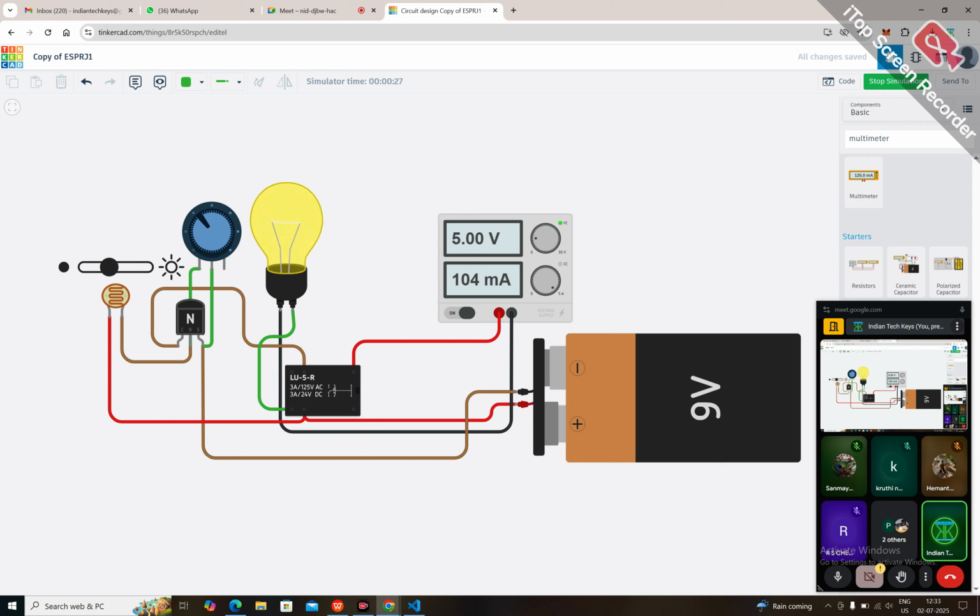Yeah, like I'm keeping it like this. Now you observe. Whenever that point is crossing, then only it is turning the bulb on and off. So till this intensity, it is turning on the bulb. Sir, for this intensity, I want to turn off the bulb. Means increase this potentiometer slightly. Yeah. See now, below that it will turn on, above that it will not turn on.